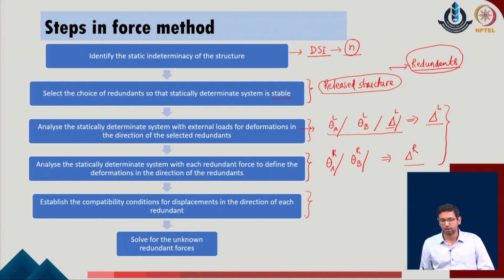should be satisfying the actual conditions which are provided in the direction of those redundants, and those are the compatibility conditions. So, we say delta is equal to delta due to the loading component plus delta due to the redundant components in the given system, and as we know the original conditions of the given supports, we can define these compatibility criteria and then we can define the number of available equations which are same as the original number of defined redundants of the given problem, and we can solve them for the unknown set of forces or the redundants of the given problem. So, this is a standard approach which we typically follow to evaluate a standard force method.